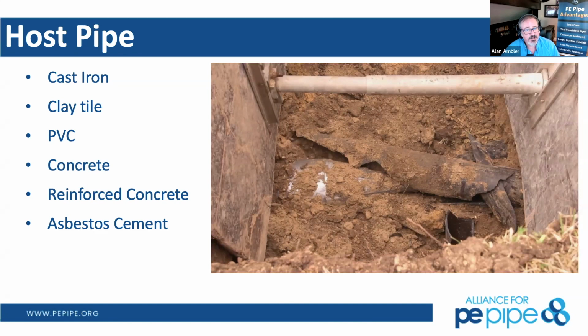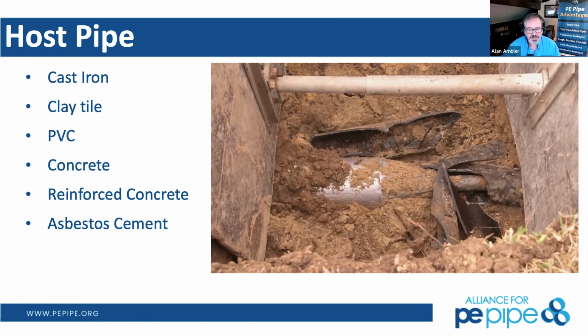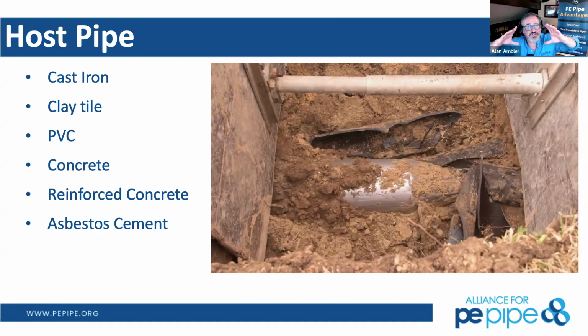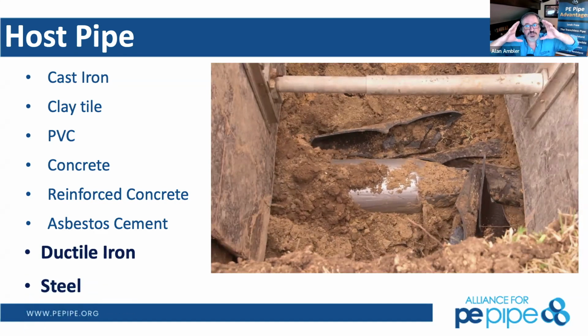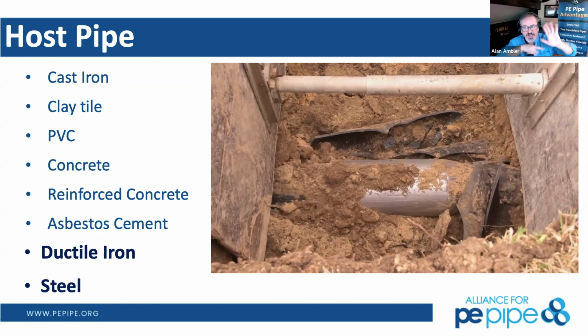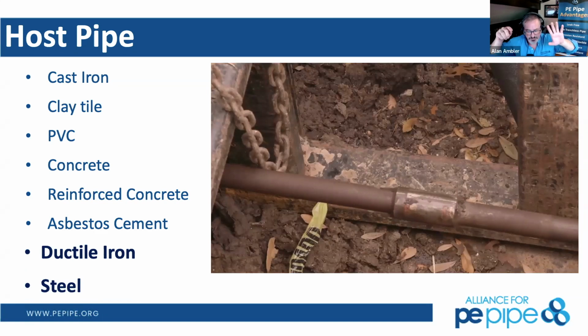So corrugated metal pipe and ductile iron pipe are both in the developmental phase. Now, ductile iron pipe will fail in a different fashion from cast in the fact that it will want to return to its original shape. Cast, when it gets to its failure point, will fail just instantaneously. Ductile iron will actually elongate and stretch, and then it wants to come back out.